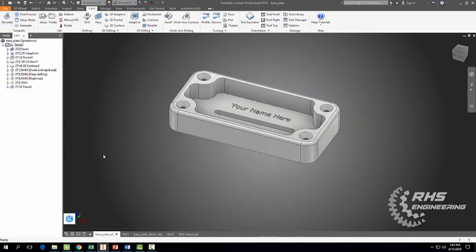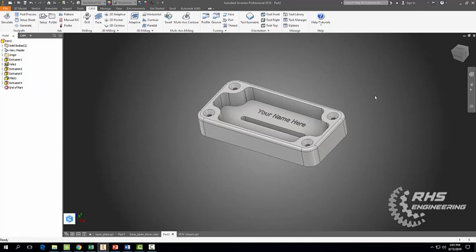First thing you want to do is to open up the part that you made the other day. Open it up with Autodesk Inventor, and at the top here you should see a CAM tab. So go ahead and select that tab and come on over here and select Setup. Once you select that CAM tab, we're going to do a new setup. So go ahead and do that.